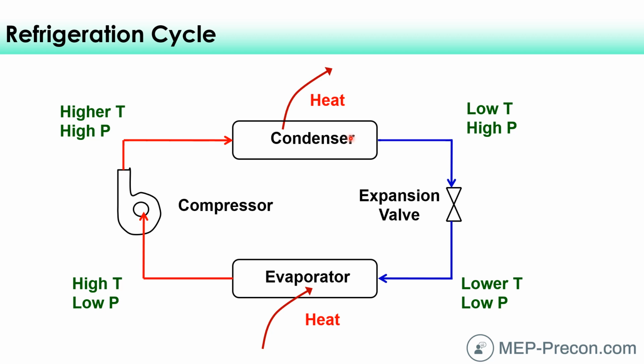Let me give you one other analogy to make sure you understand the concept of this evaporator and the condenser here, and I'll explain it in some terms that I'm sure that you're familiar with. So as an analogy here of what's happening within this evaporator, imagine having a pot of water on your stove, that would be a heat exchanger, and then filling it with water, that'll be our refrigerant. You put heat into it, that's kind of the heat of the air in this case, and on your stove, eventually that water is going to boil, right?